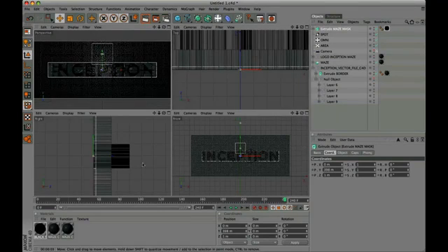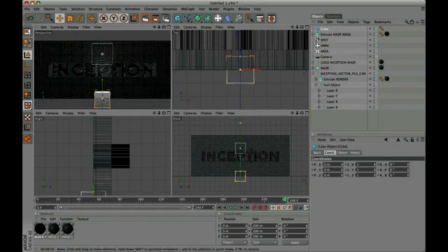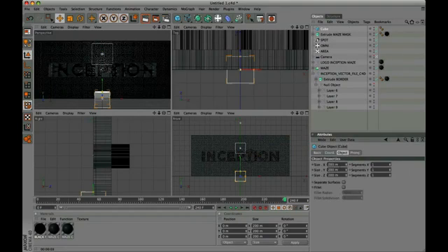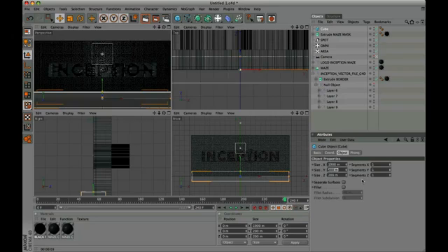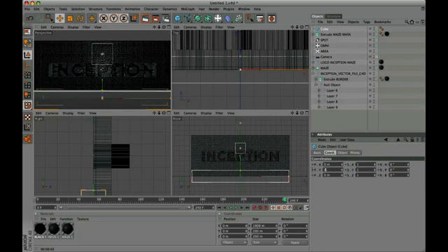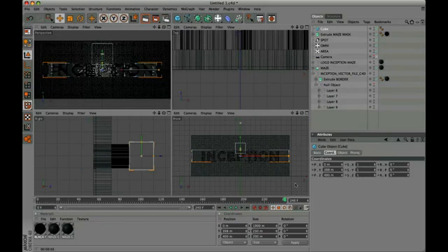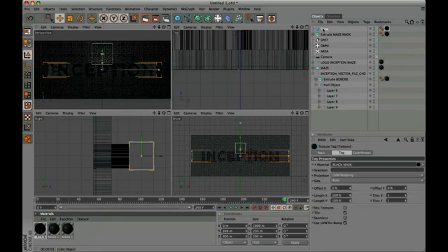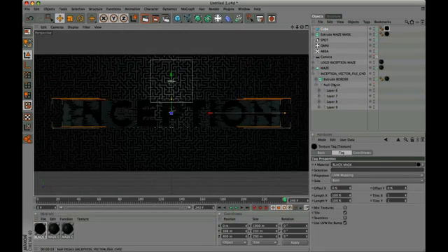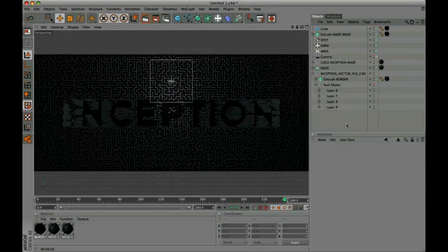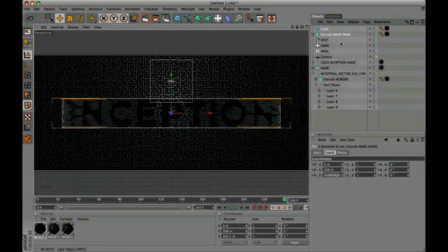Insert another object to mask the back of the logo. We insert a cube with the following values, 1900, 230. In the coordinates panel, Y 398, Z 400. Apply the material Black Mask. Select both objects and group them into Black Mask.